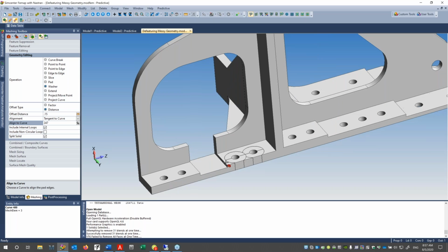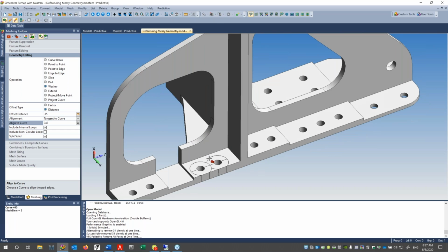I know I'm sort of obsessive compulsive on meshing, but it's when you start doing a lot of washers and you're trying to get a really good mesh, and you're doing aerospace work, and you know people are going to be reviewing it, and your quality and stuff, and it sounds weird, but you want your washers to be sort of aligned right. And the reason why we use washers on our connections is that when you're doing RBE2s on your washers, it really is nice to use a washer and use an RBE2 because it gives you better, more realistic behavior. So we've really been keen on washers on everything.